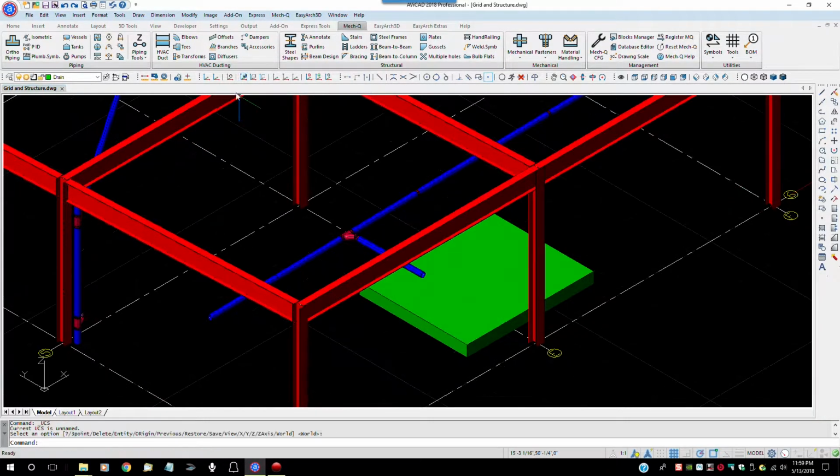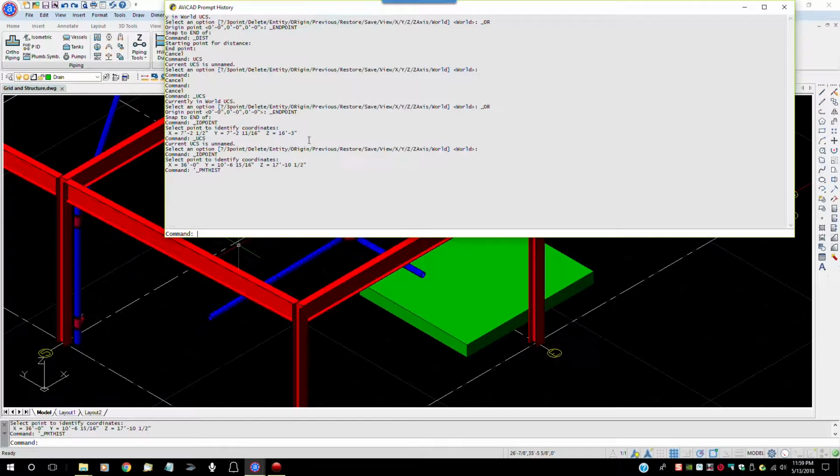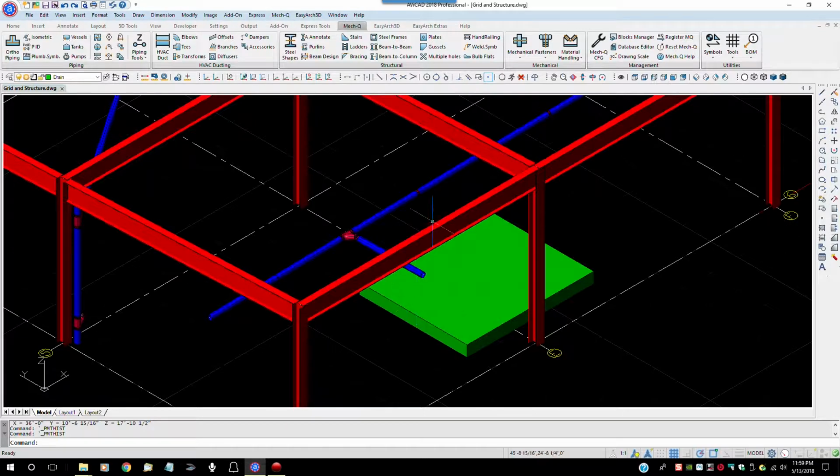And if I go back, the one that's going to be on your drawing is going to be off the finished floor. In your case, I think you guys call it the platform. So that's 17 foot 10 is what your drawing would say. And what you'd be really referencing off of this point would be 16 foot 3. We did all that without any math or having to add it, or without getting the engineer's drawing out. So that's another thing you can do if you had access to it in the field.